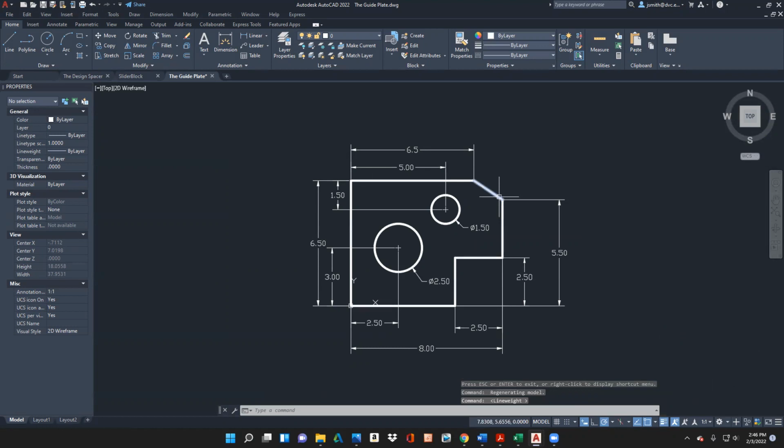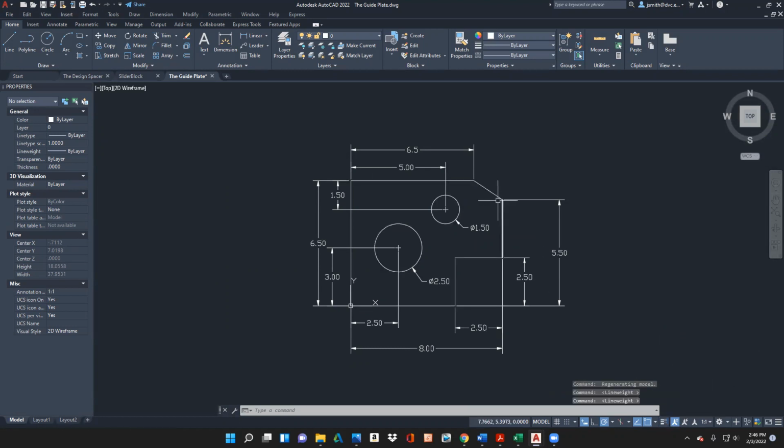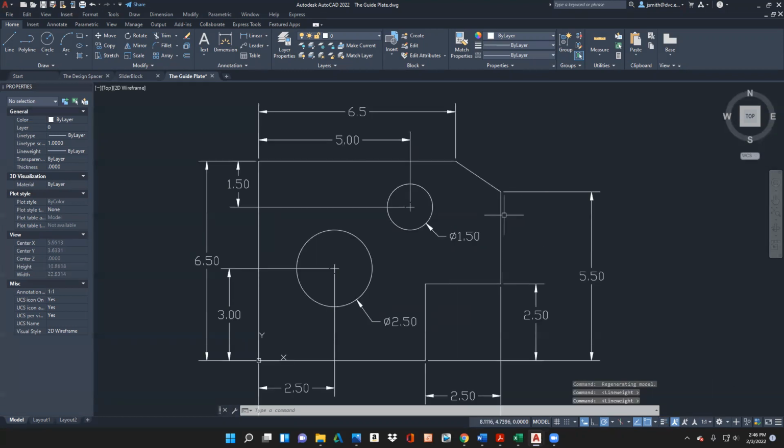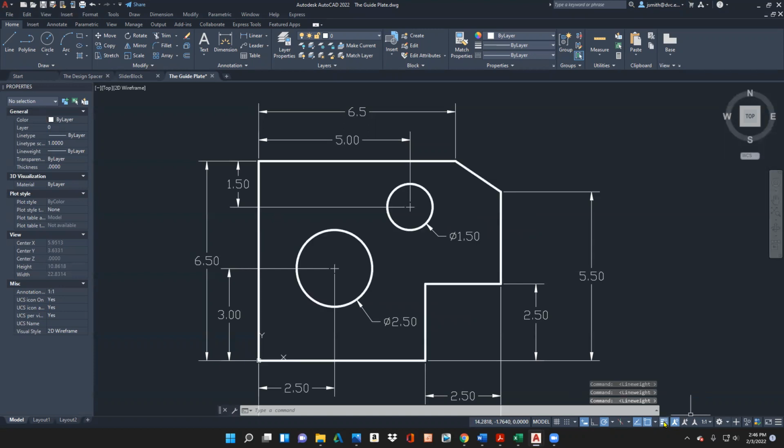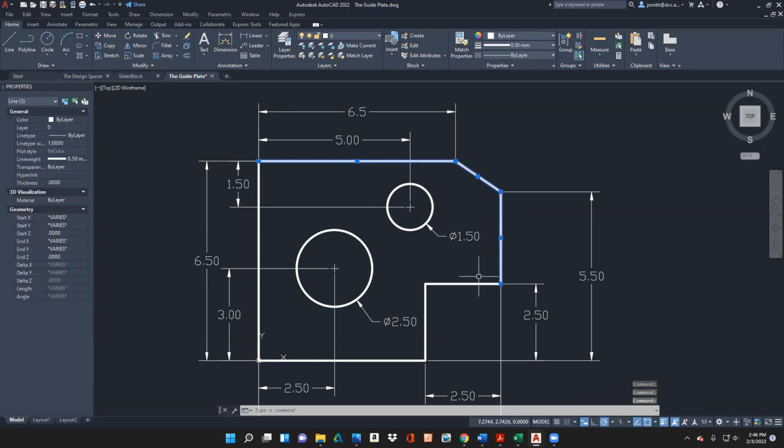And so the reason why you may not have it is it can be a little tricky as you're snapping and moving around and grabbing things when you have a very thick line. To change these lines, what you'll do is I'll kind of go backwards. So the part line generally wants to be thicker, actually it does, than the dimension line. And you always want to have that little spacing also, if you notice in the center mark.